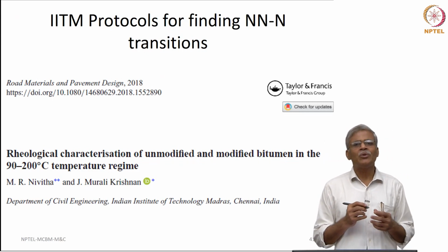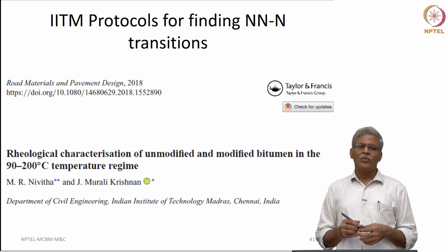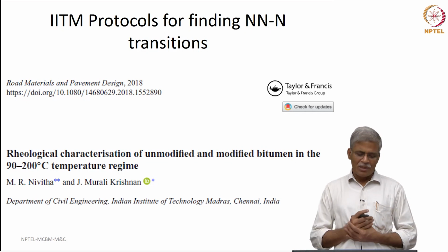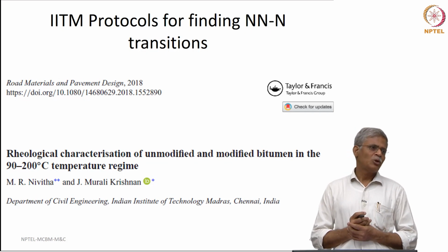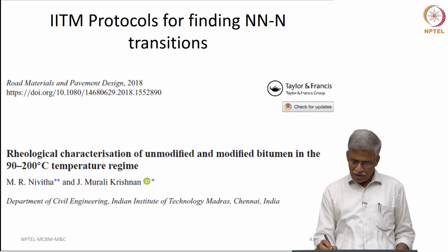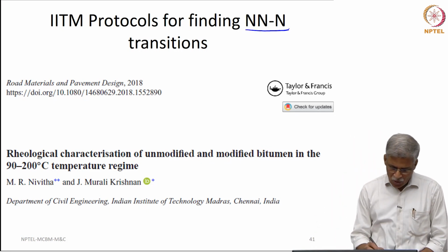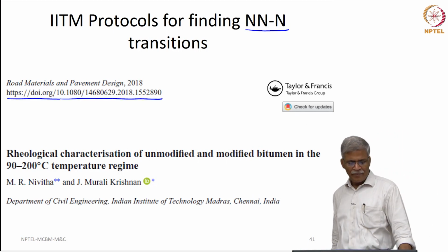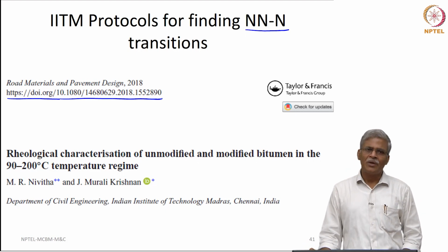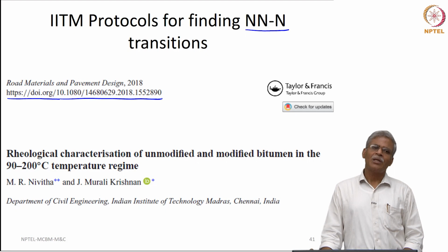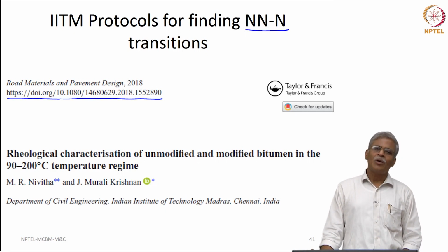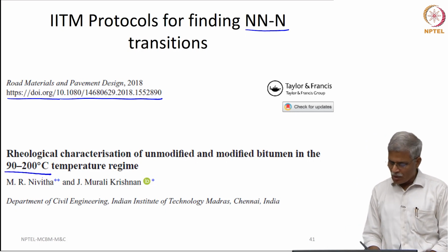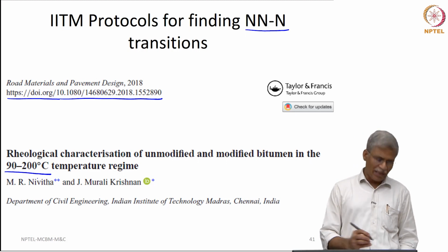And we actually at IIT Madras, and in fact with Dr. Nivita, Dr. Padma and a few others, have tried to establish some test procedures for finding out the Newtonian to non-Newtonian transition. If you are really interested, you can always take a look at this particular paper published in Road Materials and Pavement Design, in which Dr. Nivita was able to characterize the rheological response of unmodified and modified bitumen in a wide range of temperature, 90 to 200 degrees centigrade. These things are characterized. Okay.